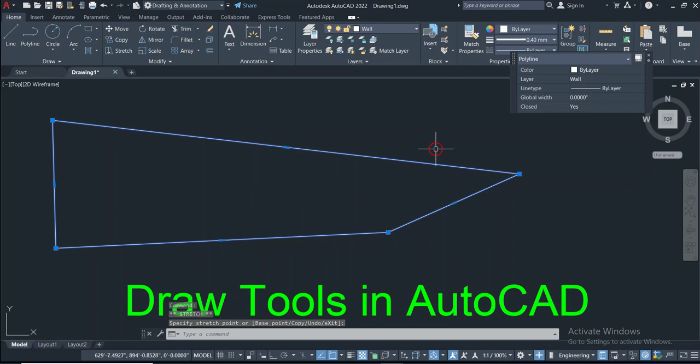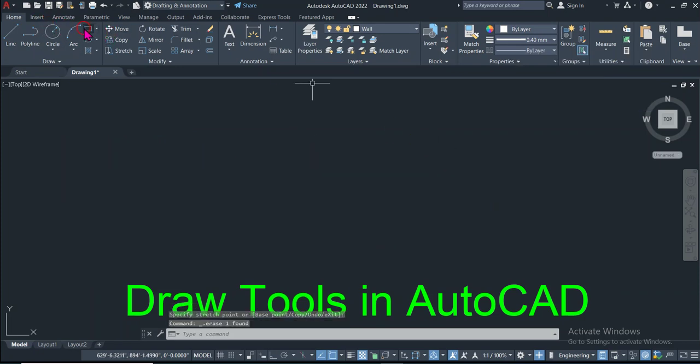So the next tool that is available in these draw tools is the polygon. When you click on the polygon, now you can see in the command line it requires you to specify the number of sides of the polygon. So we assume that there will be 8 sides, and then enter. Now you can see in the command line it requires you to specify the center of the polygon. So let's suppose this is the center.